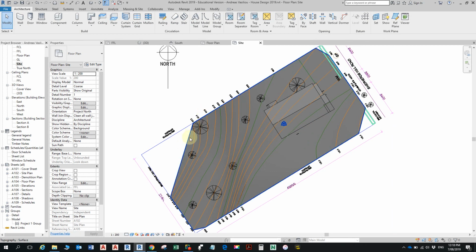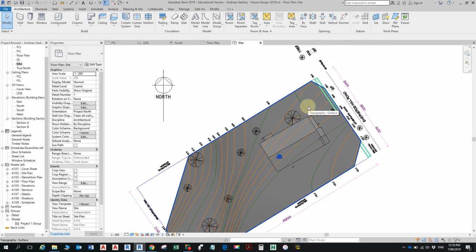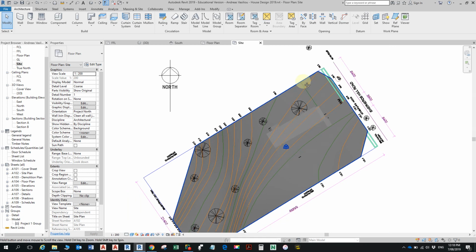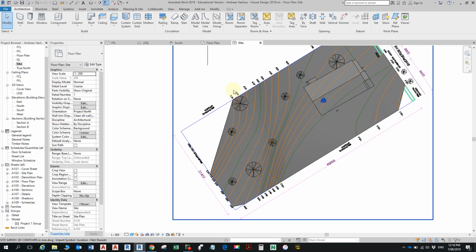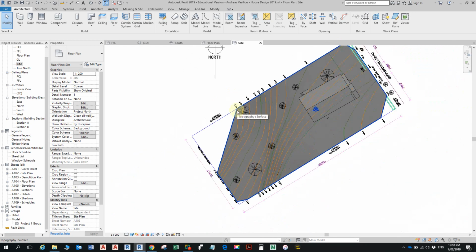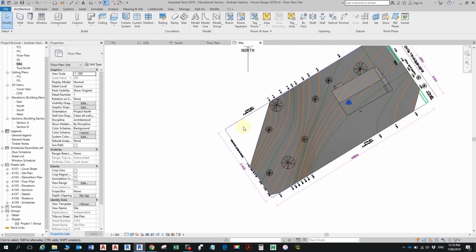All right. So if I highlight this, why is it cut off there? That's the question. It's cut off over here, it's cut off over there, right? Can you see why that's a problem and why it happened? Well, it so happened that my contour finishes there. And I'm guessing that that's the last level, which is 97.2. And then it goes flat, or they haven't surveyed it. And it's 97.2 here as well. Okay. It's the edge of the earth. Yeah, you fall off after that. Actually, that's a technical surveying term.